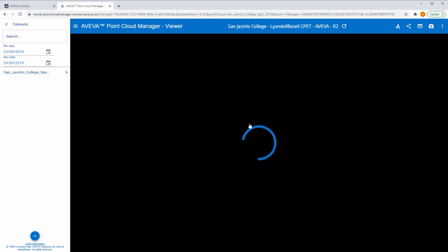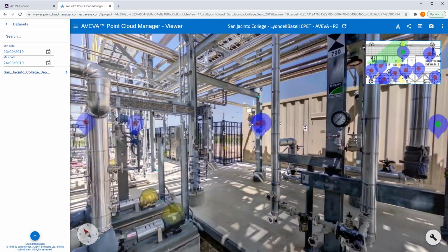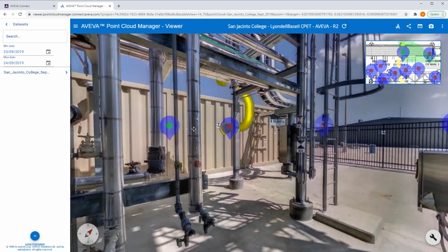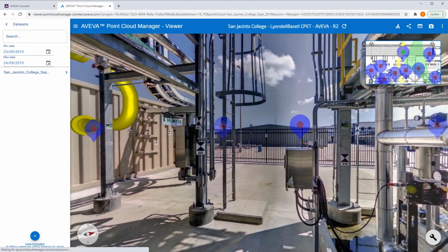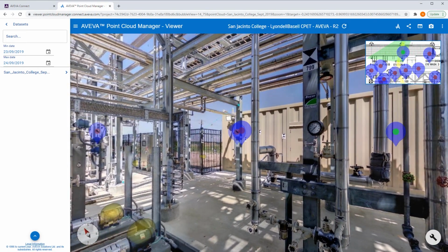Scan markers are also displayed within nearby bubble views with obscured and distant scans identified. Display range is a user option. A series of measurement tools allow the user to extract positional and dimensional information of the scene. Measurements are taken in 3D space and appropriate user feedback is applied. Measurements may be categorized and stored with the project or discarded as not required in future.